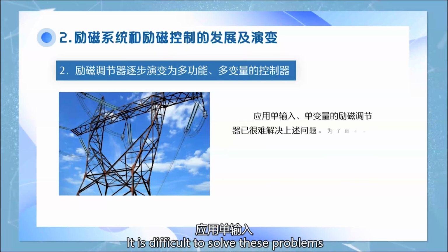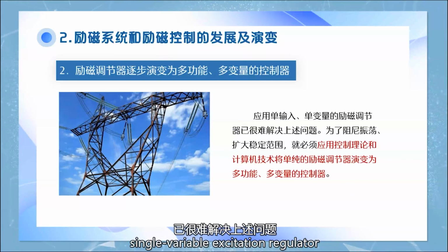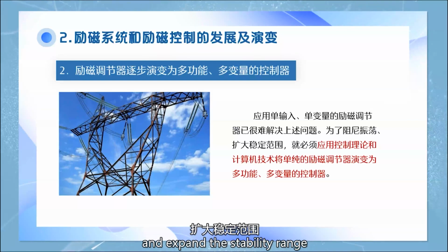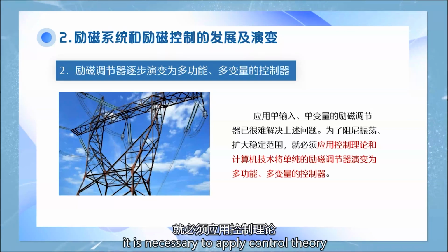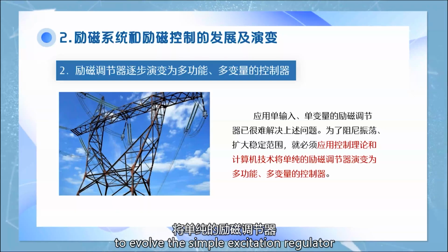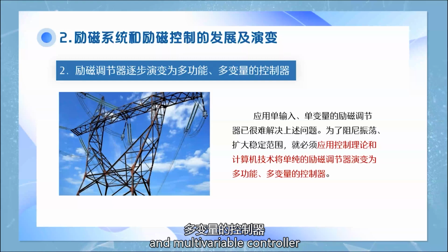It is difficult to solve these problems with a single input, single variable excitation regulator. In order to damp oscillations and expand the stability range, it is necessary to apply control theory and computer technology to evolve the simple excitation regulator into a multifunctional and multivariable controller.